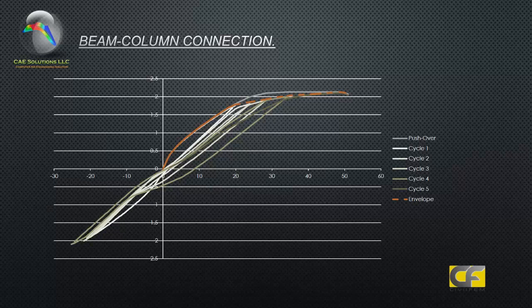this curve gives us a little more energy to dissipate. And this is why: the pushover, the monotonic loading, maybe cannot capture the degradation and the loss of stiffness due to crushing and buckling of the reinforcing bars, and the cyclic behavior can capture this information more accurately. And we can gather all that information and we have the point for comparing. Okay.